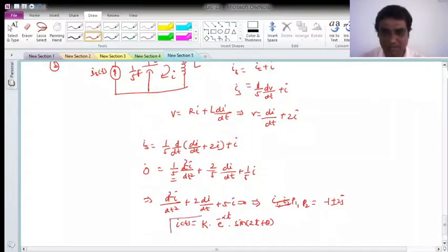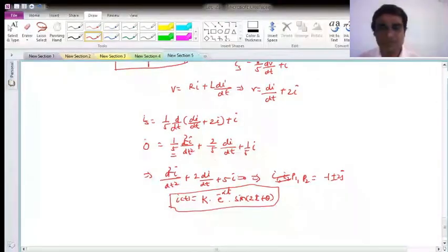This is the standard form we have already seen. Thus, if the current source is connected, I got the damped sinusoidal. It is to be noted that the conclusion we can draw is that the order of the circuit also depends on the energy source, which type of energy source you are using for the circuit.